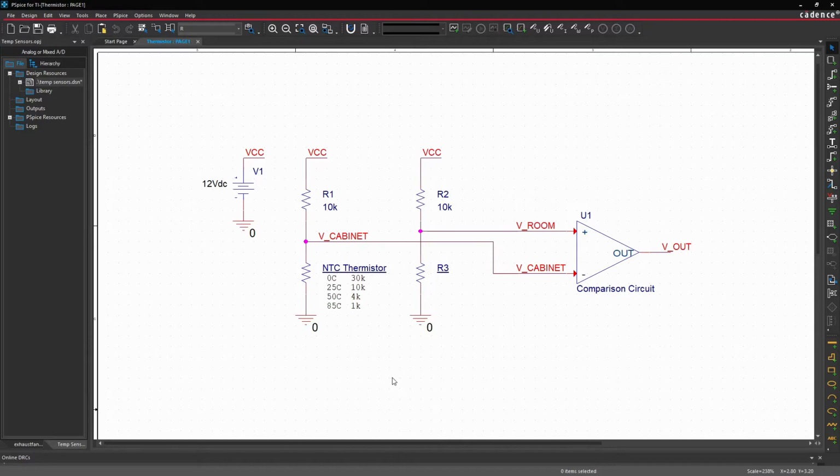this. Basically, you can just hook them up in a voltage divider like this, and then you can measure the variation of resistance at the output as a voltage. For the comparison voltage, you have a few choices. R3 could be just a resistor of a fixed value, for example 8 kiloohms, and that would be your trigger point. You could make it adjustable with a potentiometer, or you could use another matched thermistor to give a comparison